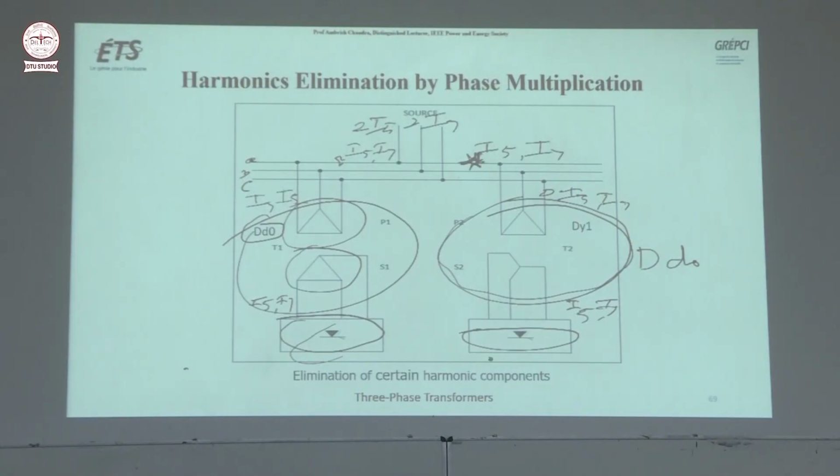And he was showing me the diagram. And he told me, Professor, you told me this in the course, and I see now there are 6, 7 multi-MVA transformers, and they were having phase shift with respect to each other. So this is not only for small load, even for large size load it is very important to see what harmonics are being generated.